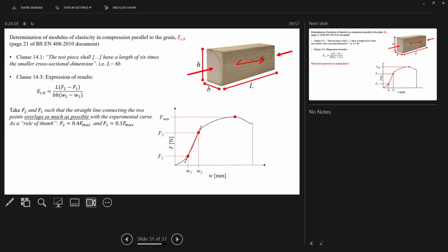So we start off, we take the F max and we multiply by 0.1, that's 10%, and we get a node there at 10% of that. Then we get a node at 40% of that. Actually, looking at my graph it's maybe a bit out of scale, but it's only a pictorial, right? So that should be 40% of that. Now, I have used the term approximate. Why would that be? And why have I drawn this linear line, or I've tried to draw a linear line here? Can anyone remember my first lecture, when we talked about plastic and elastic?